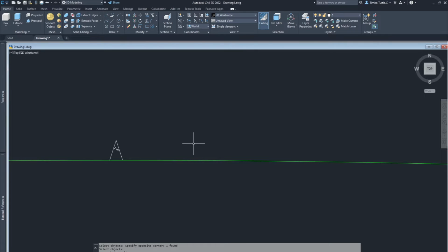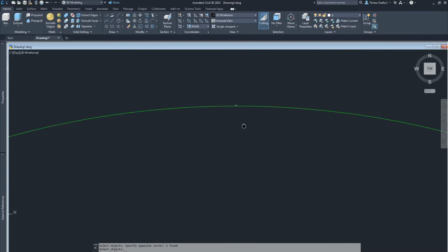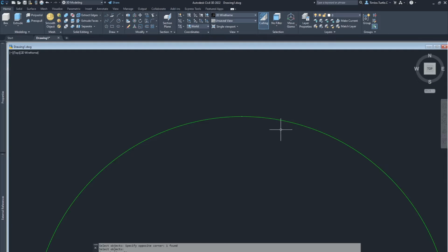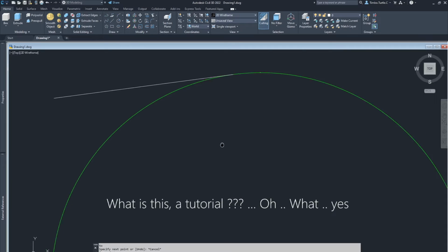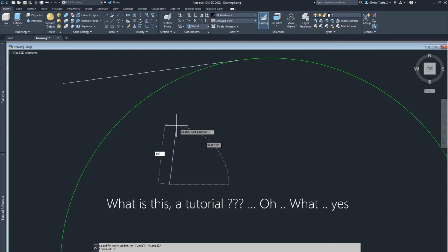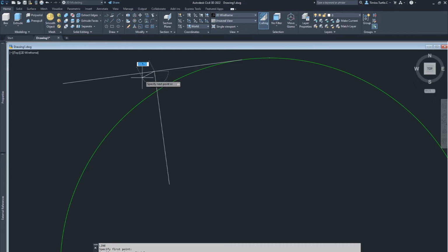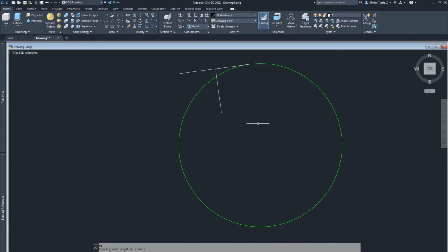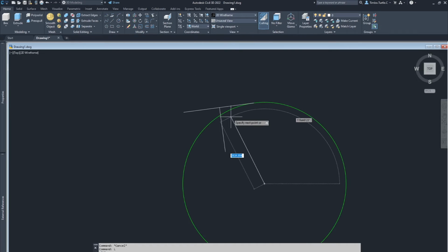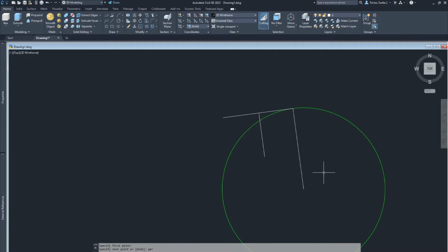and there's our line and the other one. Now, so that's pretty much the basics of AutoCAD and all that sort of stuff. If you want to draw a line, draw a line. There's a few commands in there. If you wanted to draw a tangential line, draw your line, type in tan for tangential, and you'll see that'll make a snap to the line. If you wanted to draw a line perpendicular, pick a point, type in P for perp, and you'll get perpendicular. If you wanted to draw a line perpendicular to a center, draw your line, get your center snap, as I told you before, type in perp for your perpendicular snap, and you'll get the line perpendicular.